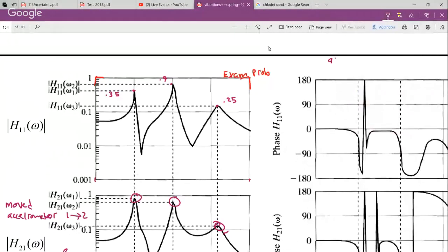So if you wanted to write a mode shape for that first mode, it would be those three numbers. What were they again? 0.3, 0.9, 2.5. If you wrote those as all positive in a 3-by-1 vector, that would be a reasonable estimate for the first mode shape. What if you put a negative sign in front of all of them? You'd be correct. They're all still in phase. All right? Good?